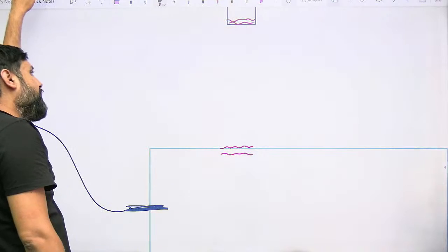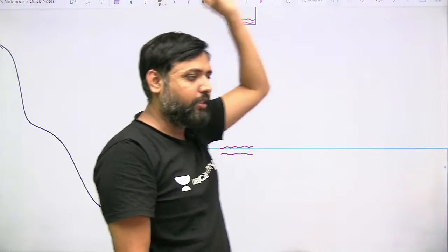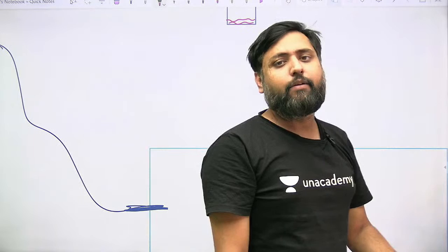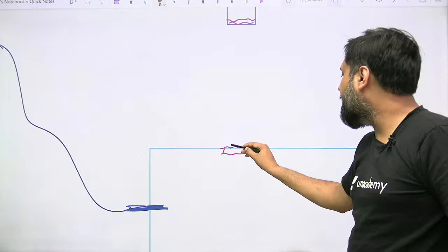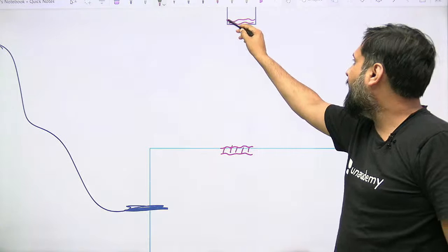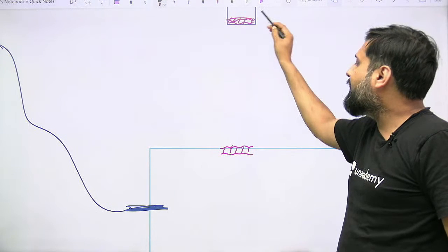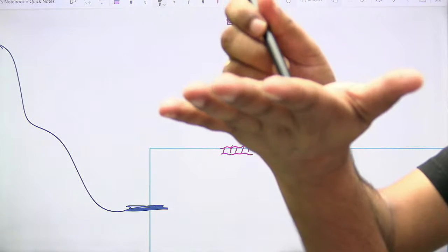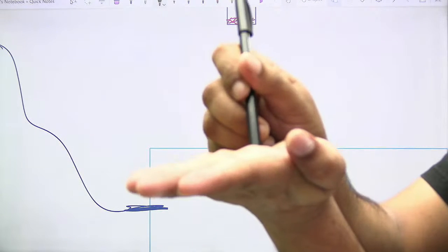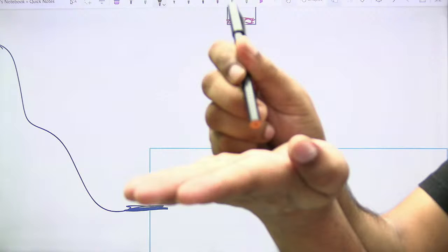Slight melting can take place due to this short circuit, but mainly a lot of heat generates at both the workpiece end and the electrode end, and suddenly the welder will bring the contact with the workpiece, short circuit will happen, and suddenly he will disengage the contact.